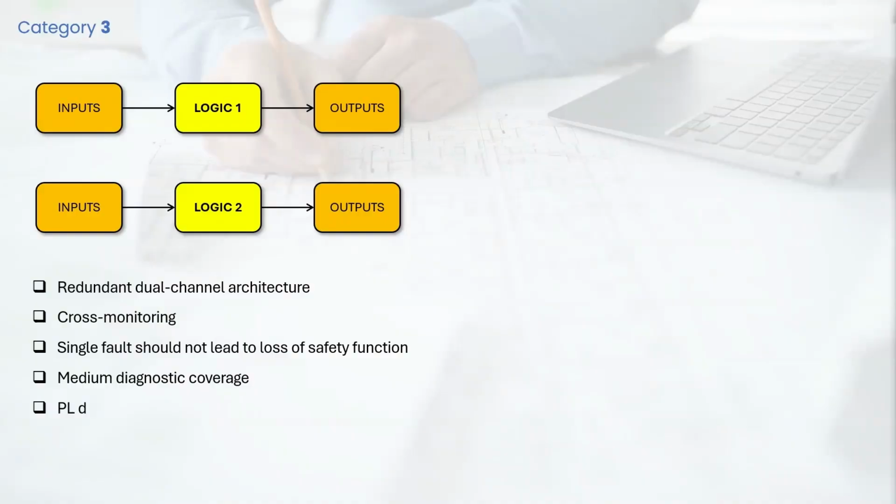The defining requirement is that a single fault in the SRCS shall not lead to the loss of the safety function. And like before, there is still self-checks and monitoring of the safety function. Monitoring increases the chance that faults are discovered before demand.